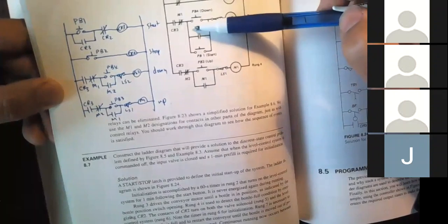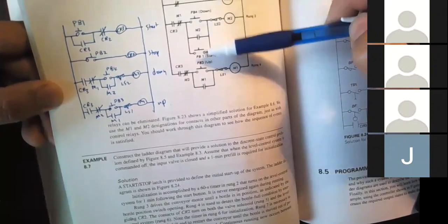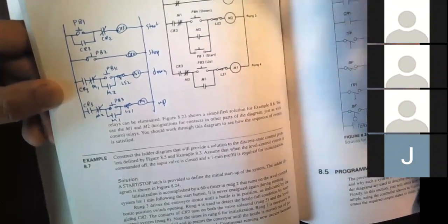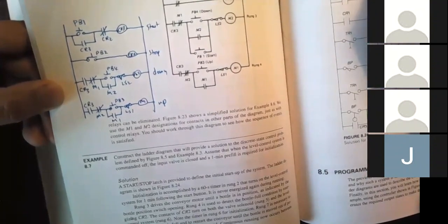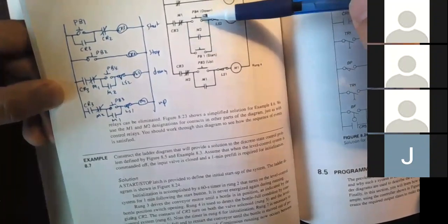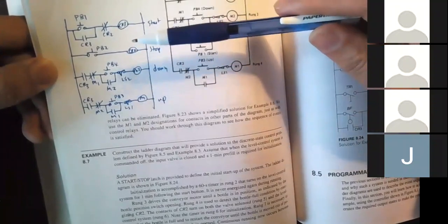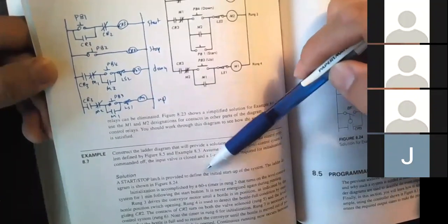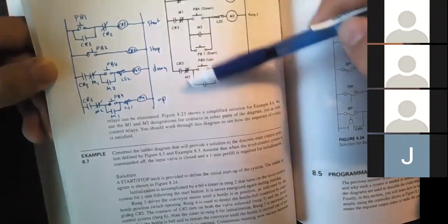The author's design, I think, is potentially a problem and a surprise to the operator. You push the start button, all of a sudden the platform moves down. You think you made a mistake. So anyway, those are two designs. One is 4 buttons on 4 runs. One is the author's, 2 buttons on the same run. I never understood this logic, why we have 2 identical buttons on the same run.